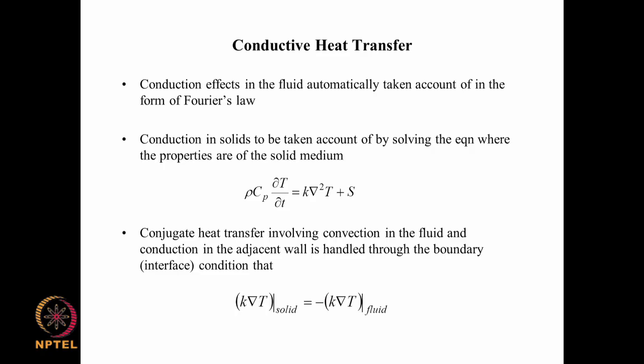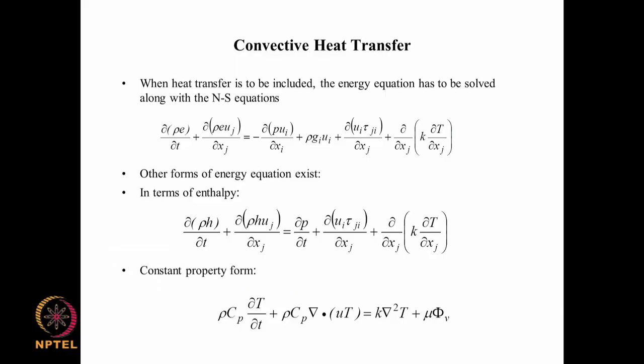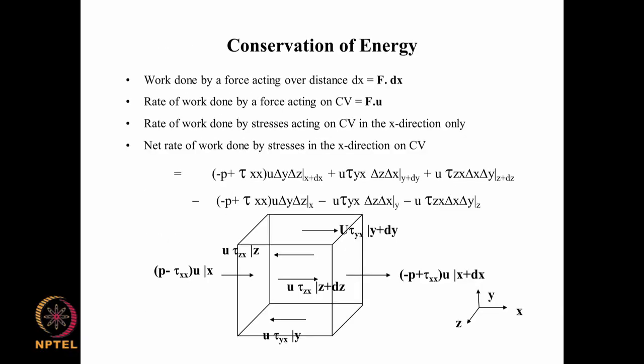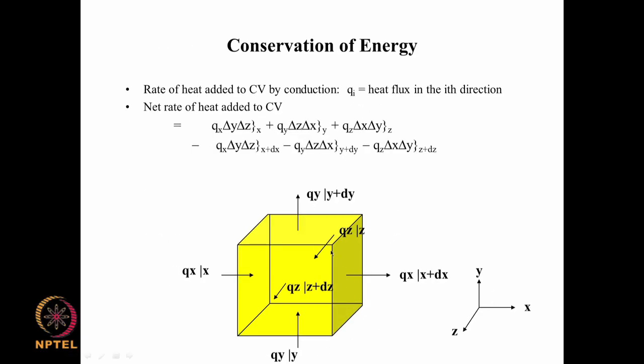That heat flux is for a minuscule control volume which is embedded in the entire fluid continuum. There we are talking about heat flux coming from the neighboring control volume into this because of temperature differences, and so that is conduction heat transfer within the medium. So, the conduction heat transfer within the medium is already included in our basic formulation in the form of heat fluxes here.